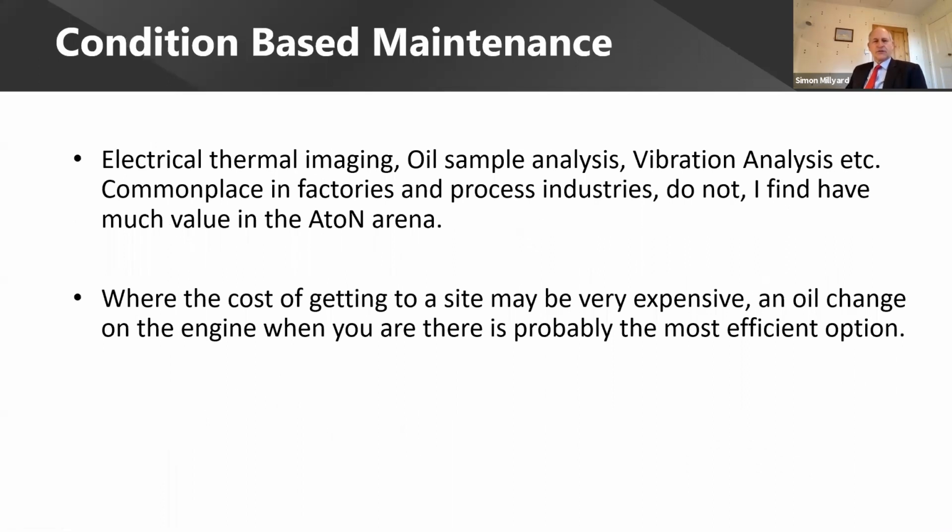Moving on to the traditional condition-based maintenance, and this is very prevalent in factories and manufacturing process industries, things like electrical thermal imaging, which is invaluable for fault diagnosis and predicting failures in a factory, along with other ones I put there: oil sample, vibration analysis.